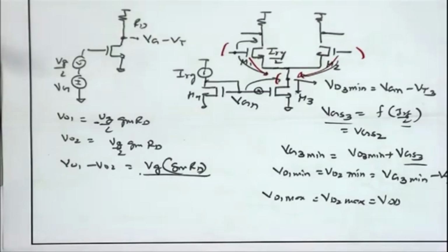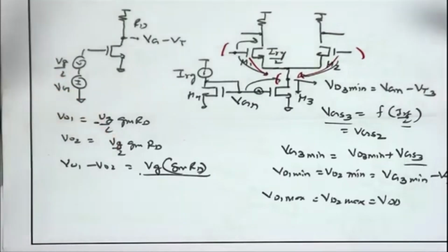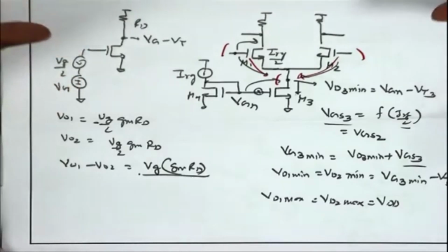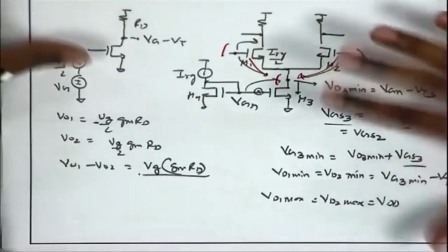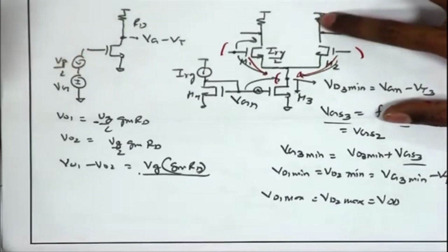Now, in case of our designs, we are going to use a differential amplifier with active load, and we have already had discussions on the common source amplifier with active load, how to do the analysis like DC, AC, small signal and noise. If I replace this RD by a PMOS load, once again the entire analysis for the differential half circuit remains the same, and the common mode half circuit once again remains similar to what we have done for the resistive case. The only thing is, rather than RD you have an RO coming over there.